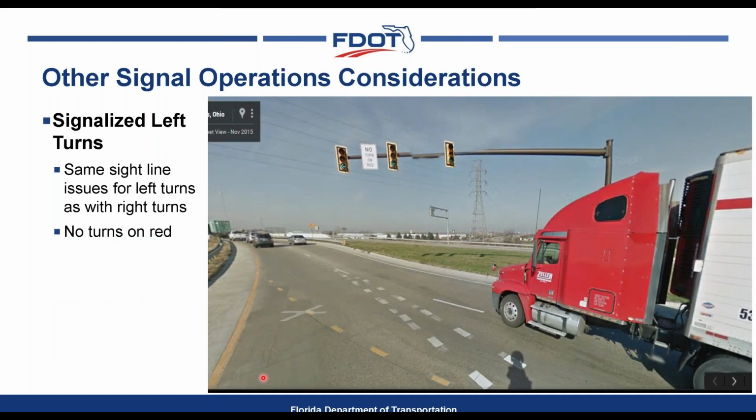And with the DDI, the same principles we just applied to signalizing the right turns from the exit ramp are the same for signalizing the left turns. The left turn should be signalized as well, again, with no turn on red.